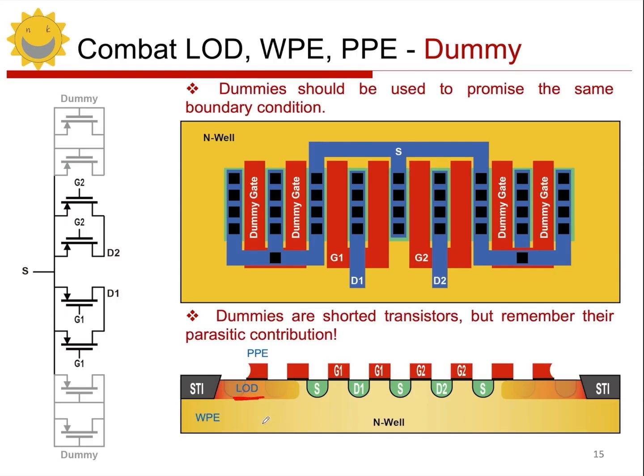At the same time, we can see what type of transistor this is. This is a PMOS, right? It's a P-type, so it's processed in an N-well. The yellow area represents the entire N-well. Now we can see that because of the presence of this dummy transistor, it also causes the transistor in the core area to move away from the edge of the well, right? The edge of the well is over here. The edge of the well is here, so this edge is further away from our core area, right? In that case, the proximity issue is also resolved, right? The proximity issue is resolved.